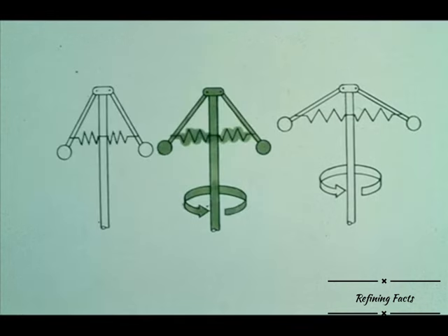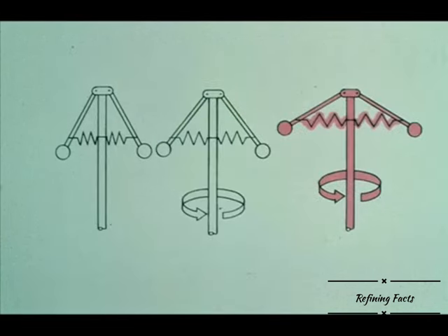As the shaft reaches operating speed, as shown here, the spring tension is overcome by the centrifugal force of the spinning weights, and they move away from the shaft. In this illustration, the shaft is turning too fast, and the weights are at their farthest point from the shaft. Remember, the farther the weights are from the shaft, the more the valve is closed, cutting down on the steam allowed into the turbine.